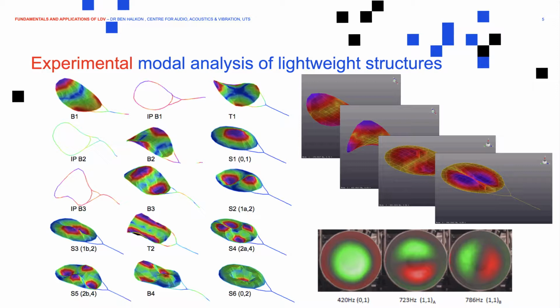Okay, so it's important how these structures sound, and therefore, as automotive manufacturers and OEMs do, sports equipment manufacturers invest heavily in the R&D around engineering the sound of a racket, of a club, of a bat, of a ball. And here are some example mode shapes that are animated. Okay, so we go from one point to the next. You can see the point of the vertices of the lines, essentially. So there's around about 50 points on this system presently. Torsional mode, and then string bed only mode.